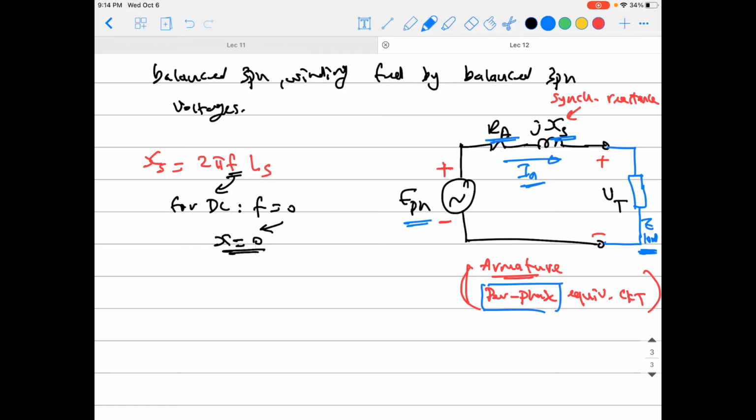That means if I give you the value of the terminal voltage in line-to-line quantities, as it is typically given, you cannot use it in this circuit directly, because that is a per phase circuit. Everything here is phase quantities, not line-to-line quantities, like we said before in the three-phase circuits review.